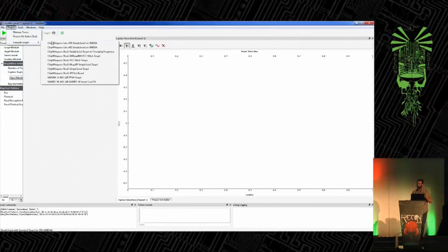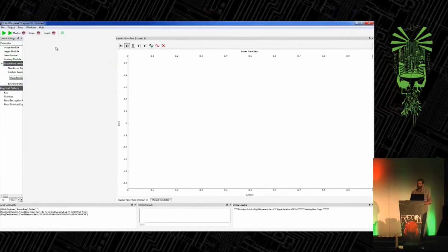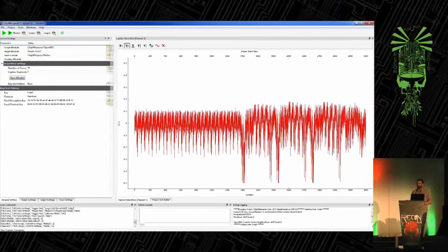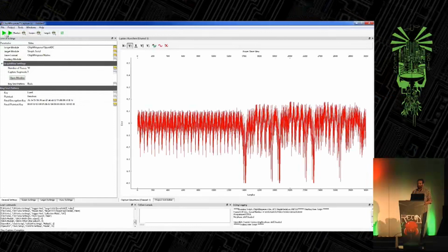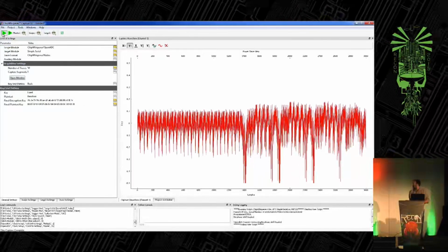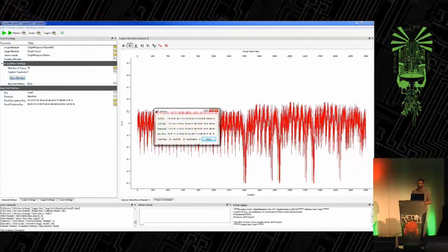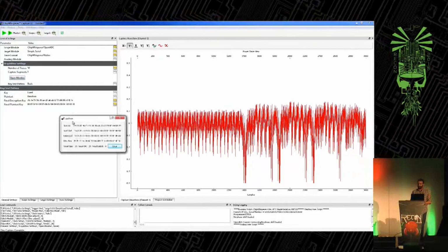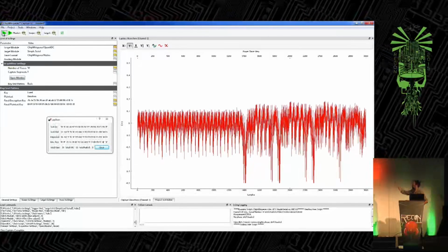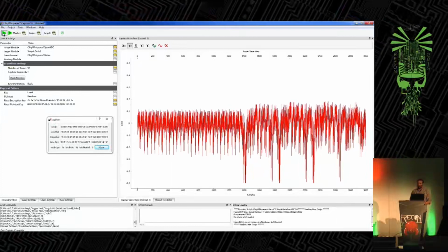And it can attach to various targets. So I'm going to be attacking AES on this little XMega board. What it's doing is sending encryption messages to the device and then recording the power. So you can see the traces bouncing around as it's recording different messages, and you can view the AES-128 inputs and outputs just raw. In this example, I'm just testing a library, so it just sends a message, encrypts it, and that's it.